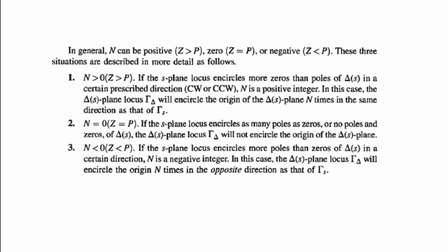We have considered an arbitrary closed loop contour in the S-plane. There are certain zeros and poles lying inside it. Thereafter we have drawn another contour, that is delta of S in some other plane, the delta plane, and if the difference between the zeros and poles is equal to the number of encirclements about the origin, the system is stable.